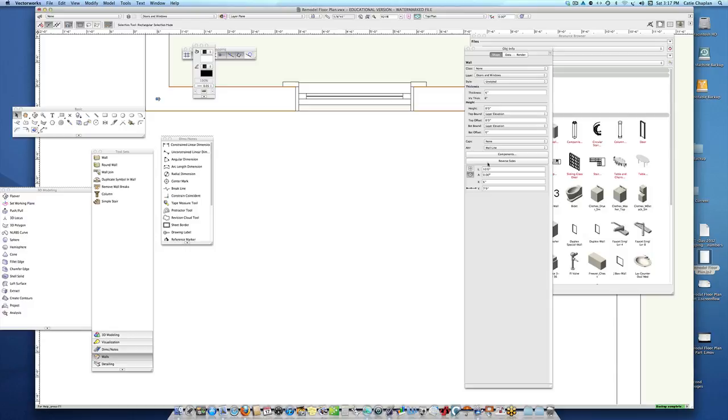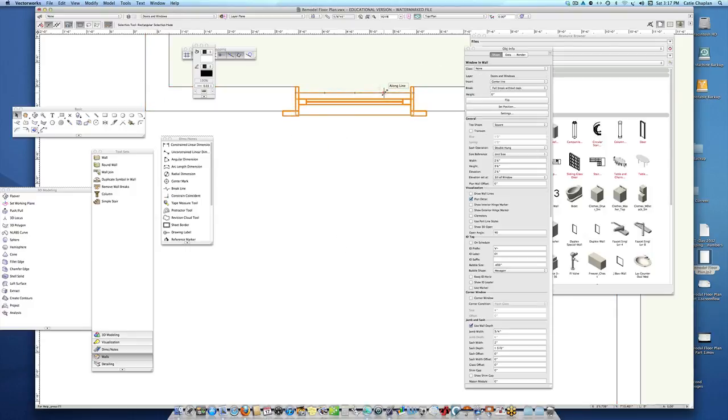And when you make walls from polygons, you don't have control over which is the inside or outside of the wall, but no worries, you can select the wall. So I've selected this one segment of the wall, and I just choose reverse sides. And there we go, my trim is drawn now on the inside. So I just need to resize this.